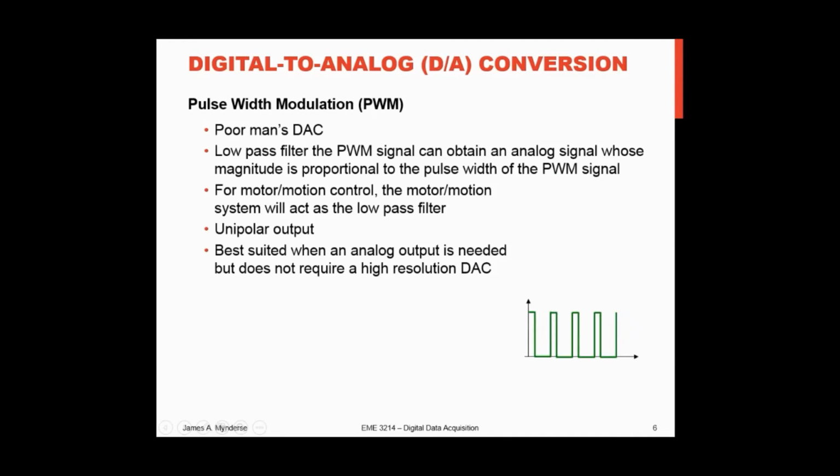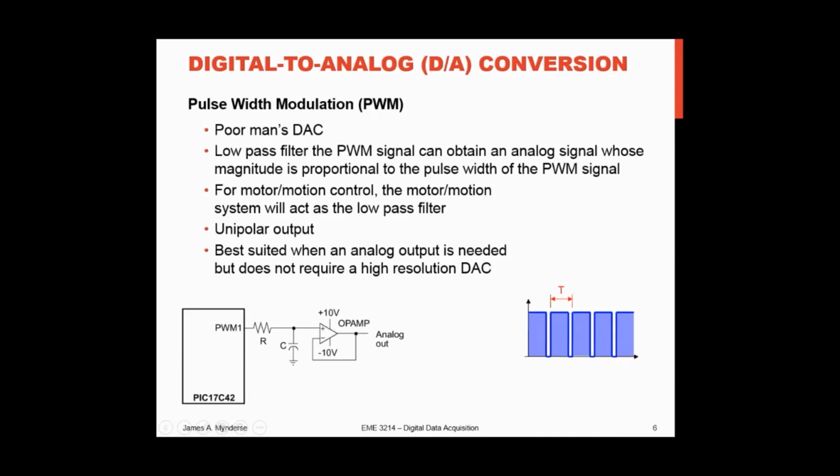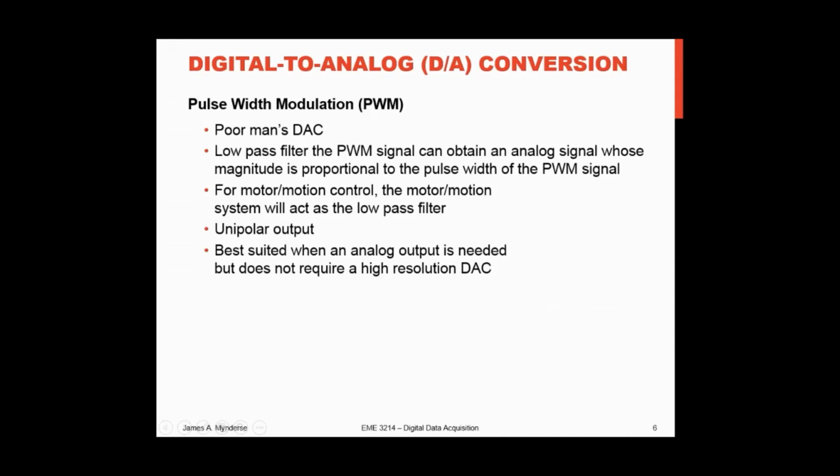And we can use that PWM in our circuitry here as essentially a poor man's digital to analog converter, because the average output is a function of how long it's on versus how long it's off. So here I have one duty cycle. Here I can change the duty cycle and make it much larger, and my average voltage is higher. There's a time period here for each pulse. That's the base time, and the duty cycle is the percent of the time on.